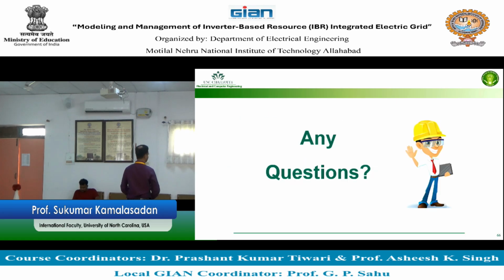So what we have learned today is in two parts. One part is we learned how you can extend the power flow and use that power flow to maintain voltage stability or voltage balance. We started from the power flow. So power flow, optimal power flow, and time series power flow is what we have covered in the last few lectures, and using that for stability as an example.